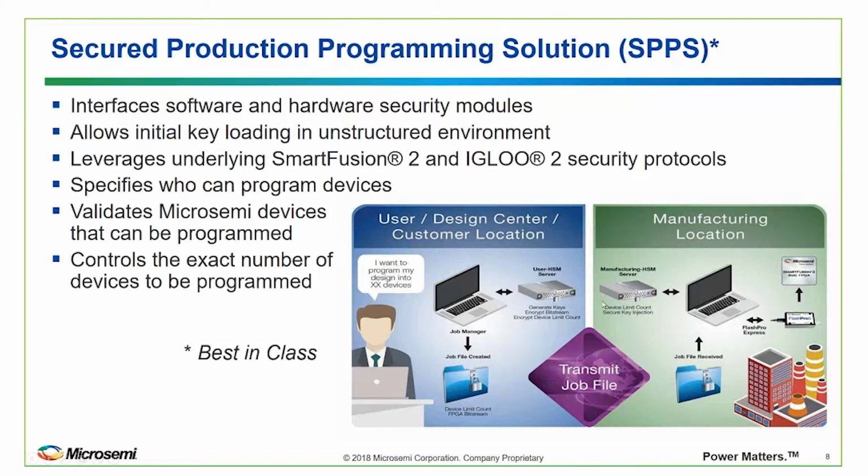And the user would go through and use our Libero software and create a job ticket that indicates the bitstream, the keys that are injected, and the number of devices that are authorized to be programmed. And that gets transmitted over to the manufacturing location and used with the HSM at the manufacturing location to allow a certain number of devices to be programmed. So this ensures that the keys are never exposed.